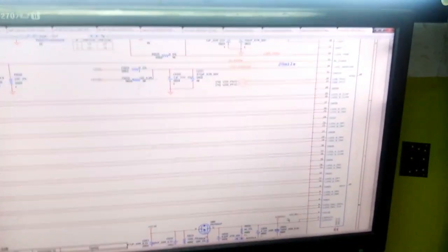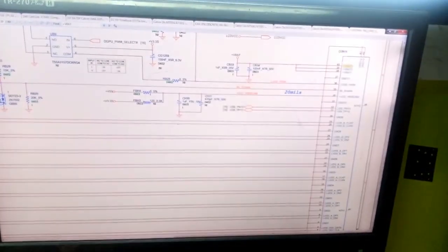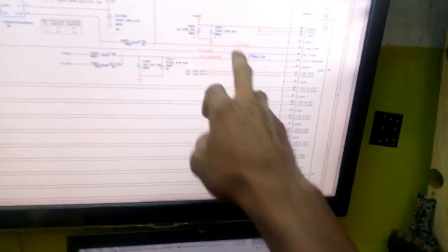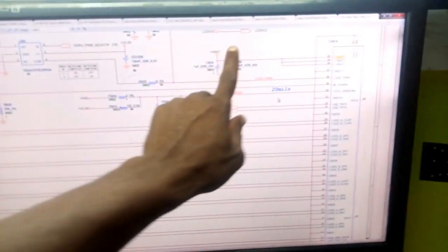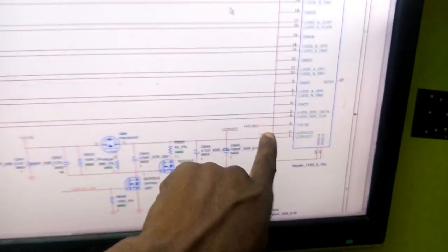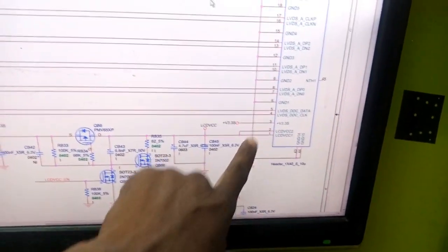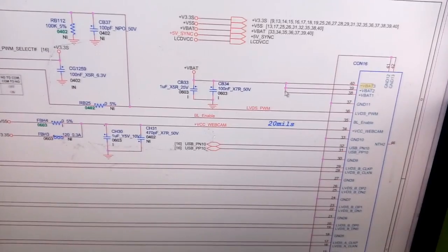So basically, I'll start from the very first one, which is pin number 40. That is the main rail of the 19 volts, the main power supply, this particular voltage. The first basic ones I need here are pin number 40, 39, 38. Then pin number 1 and 2. This one, definitely I will have pin number 3 before going for any other thing. These two later. So those are the basic ones I need first.